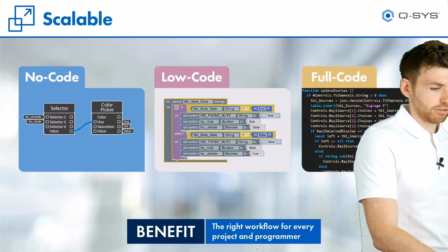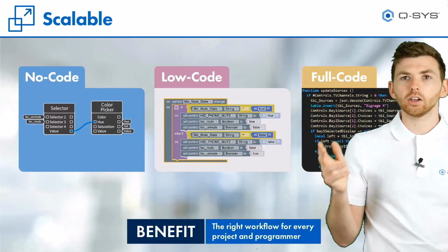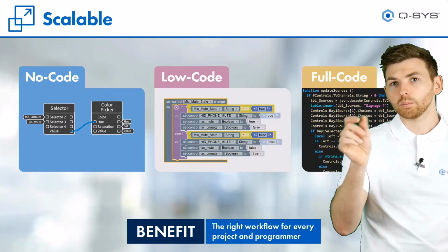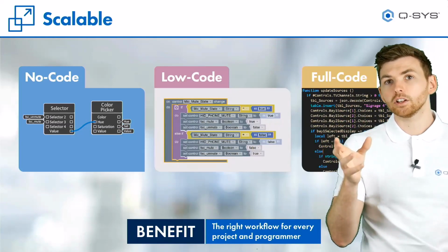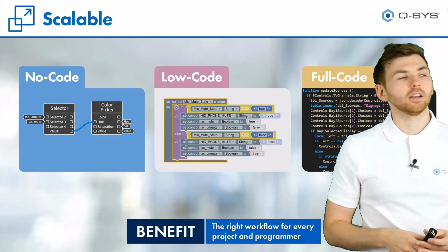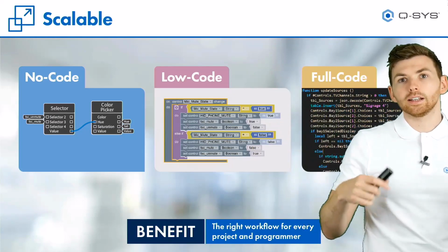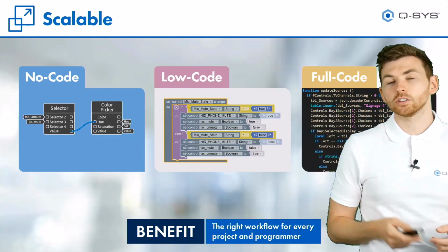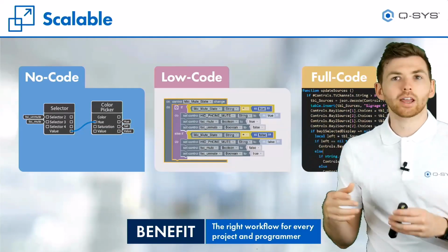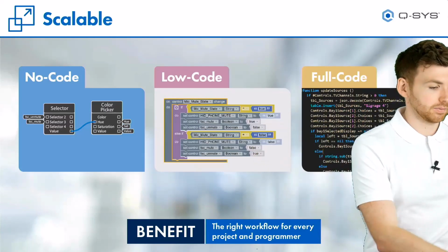We have a question here. Do peripherals include analog audio? Now, Craig, I'm not sure if you mean each analog audio channel. If you have a QIO box, the one with the analog IO in and out, that's going to be one peripheral. Also, if you added a great big Dante analog in and out box, and you're controlling that with a Q-SYS plugin, that would be one peripheral as well. So we're not looking at the number of channels or anything like that. It's just each Q-SYS box that you're adding in, essentially.